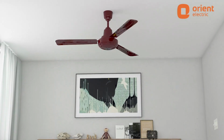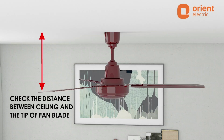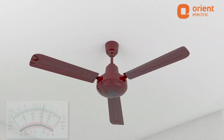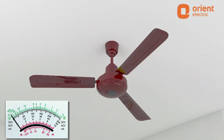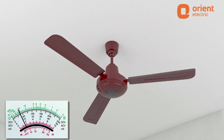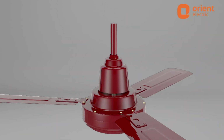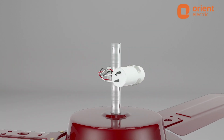If the ceiling fan is running at low speed or is circulating less air, then you first need to check the distance between ceiling and the tip of fan blade. If it's less than 10 inch, advise the customer to use a longer down rod. This low speed or low air breeze problem can also be caused by low input voltage. In this case, check the voltage and inform the same to the customer. If you find a defective capacitor during the inspection, replace it.